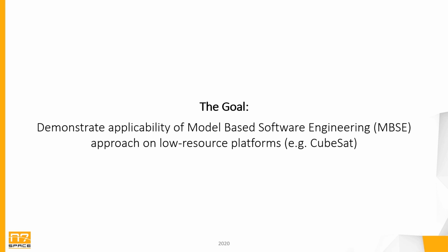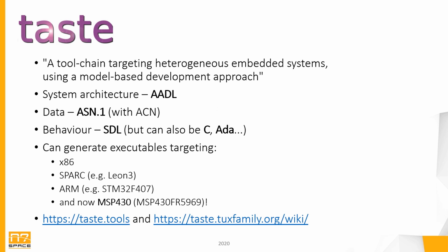those used in CubeSats. The used MBSE environment is TASTE, a toolchain developed under the initiative of the European Space Agency. It is dedicated to embedded, real-time systems and supports both model specification and flight code generation. The key technologies involved are AADL, Architecture Analysis and Design Language, ASN1, Abstract Syntax Notation 1 for data modeling, and SDL, Specification and Description Language for behavior modeling.